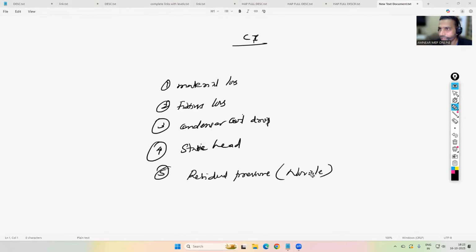We will have spray nozzles. In the critical path, for the last one or two nozzles, to overcome the pressure drop through the nozzle, we get the value from the manufacturer. That will be nearly 10 psi, approximately 0.7 to 0.8 bar. You have to consider that as the residual pressure. By adding everything together, you can calculate the cooling tower. So all these pumps, transfer pump, booster pump, sump pump, sewage lifting pump, and cooling tower pump, are open loop pumps only. Gravity, static head you have to consider for all these pumps.